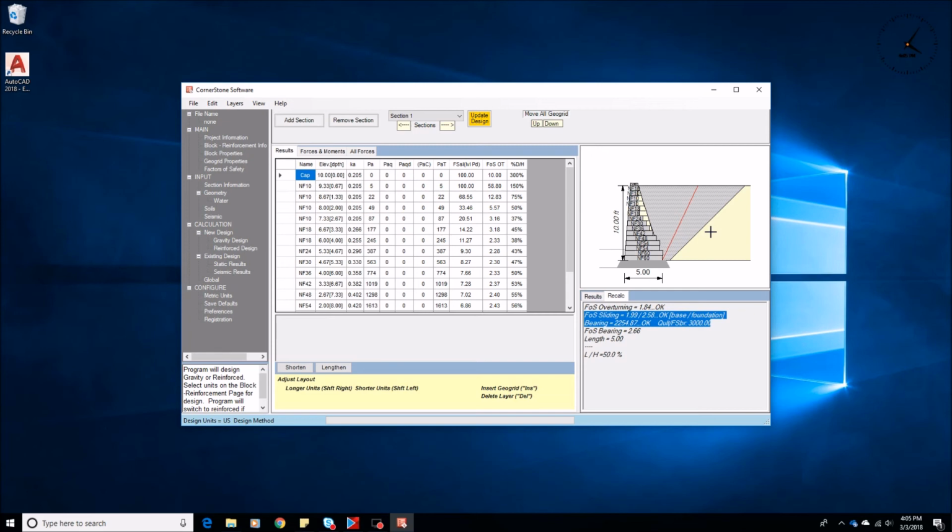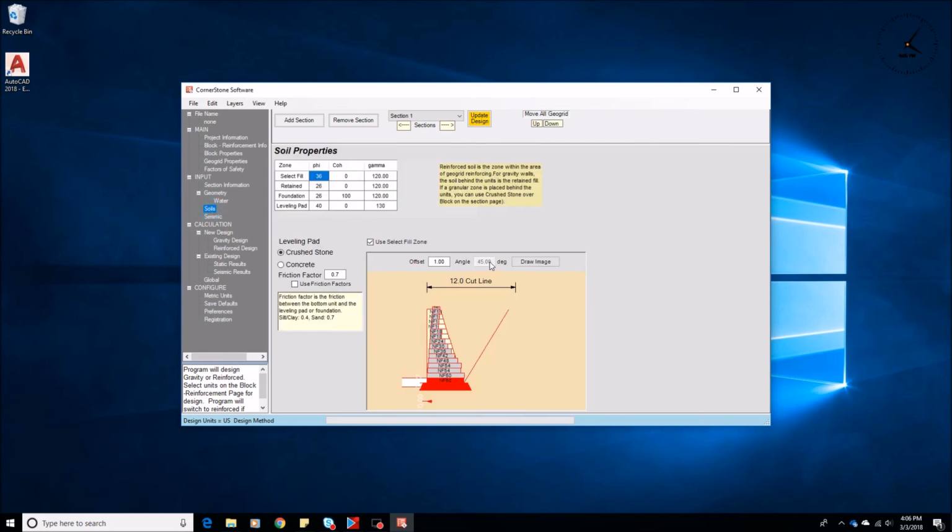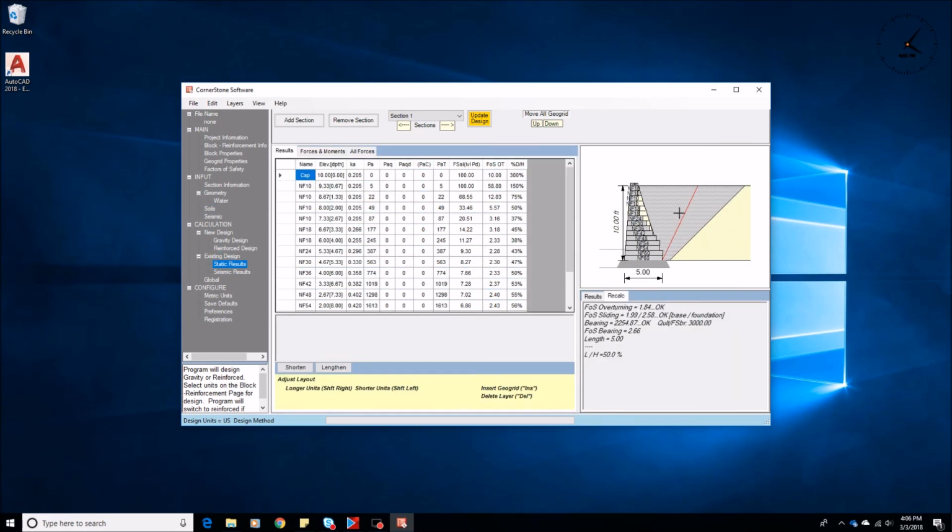In many cases where we have poor backfill on the site, clays, silts, very silty material, it's a good idea to come in there with a select soil. We go up at a 45 degree cut, fill that with a good material, and then our gravity wall is going to work a lot better. You also get good drainage in here, good compaction, much better overall performance.